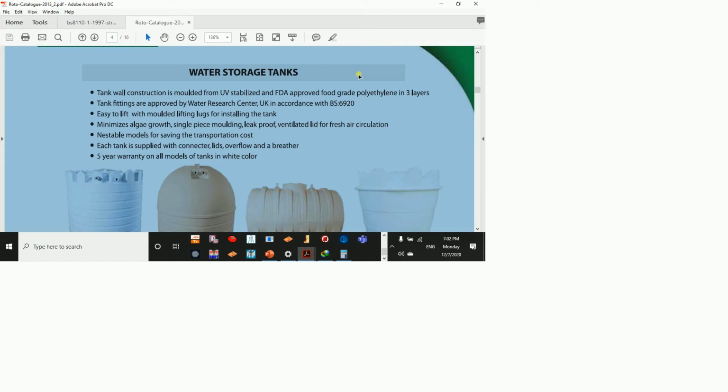It does not mean that some of the designers don't know how to design, but we are dealing with unexpected changes. Even, for example, if you are designing for a single story, the municipality will always tell you that you need to design for one more story, because you will not know when the client comes and says that they want another building. If you didn't design the foundation to take another story from the beginning, it will cause you a lot of issues.